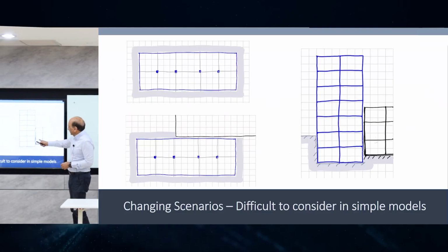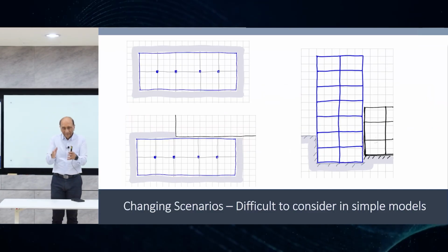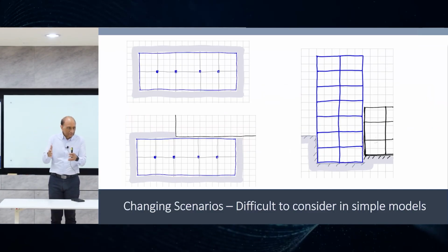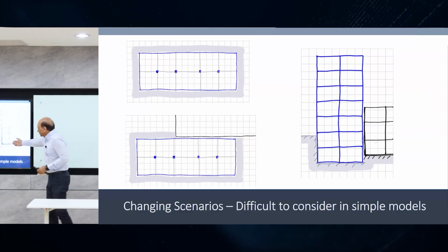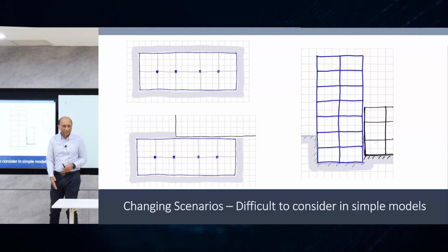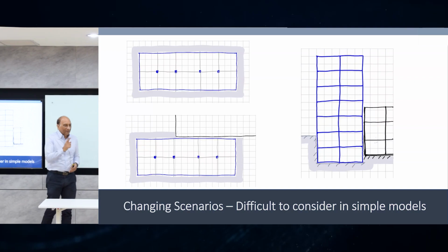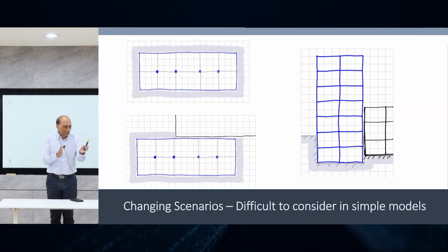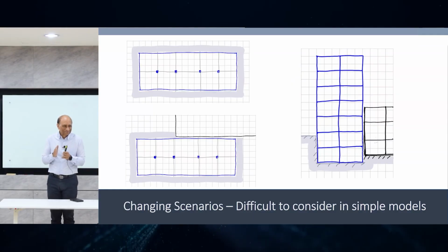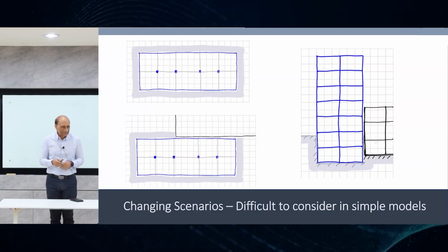In reality, things can be like this. There can be a building, and next to it there's another building, at a different height, not the same height, right? No gap. Sometimes they just construct next to your building. In most countries, they're constructed like this. In Myanmar, they have a law that even if your buildings are like that, you have to have a gap of how much? 30 centimeters in between the buildings, 1 foot. Must be separate. 1 foot, 30 centimeters.